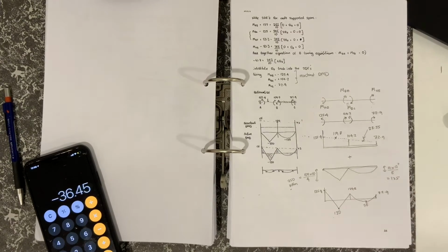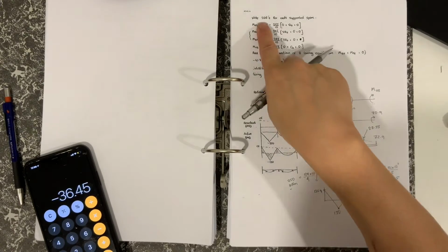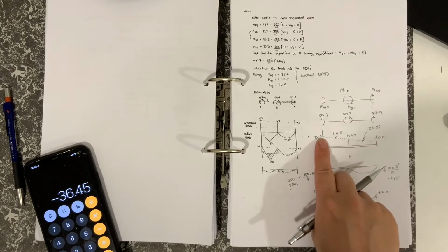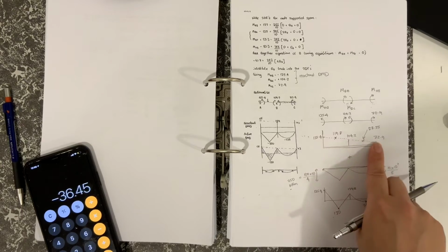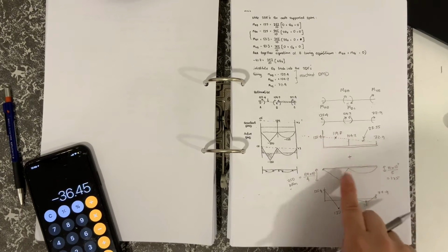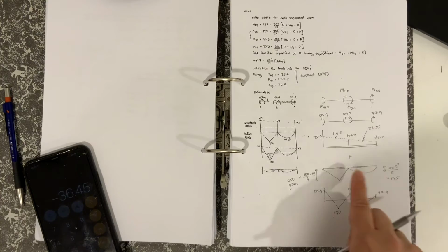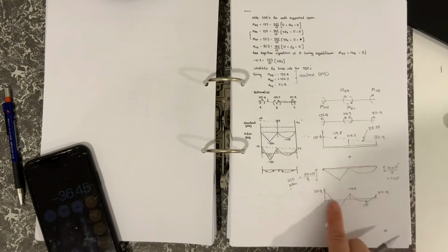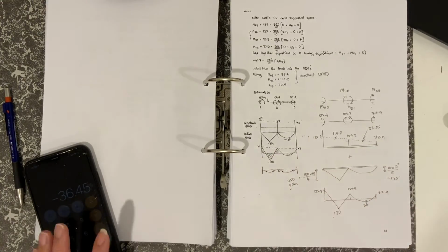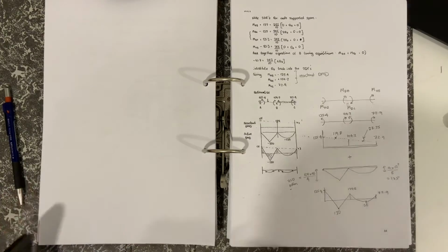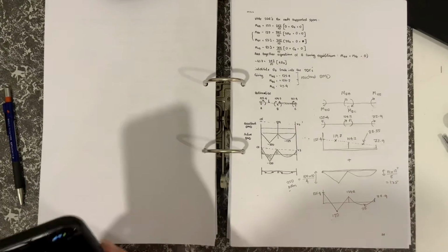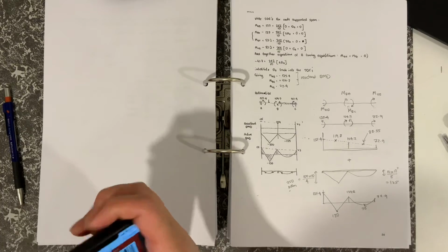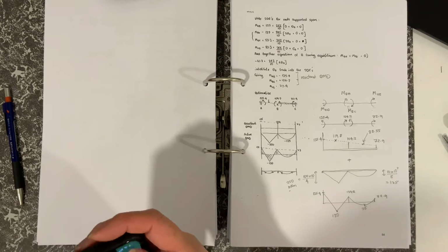So that's where you get the bending moment diagram. We've used the slope deflection method to get the reactant moments, which would be that value and that value, and then we add it onto the active bending moment, which is just the simply supported beam for each span, and then we can draw out what the final bending moment is. So that's how you can easily solve a statically indeterminate problem.